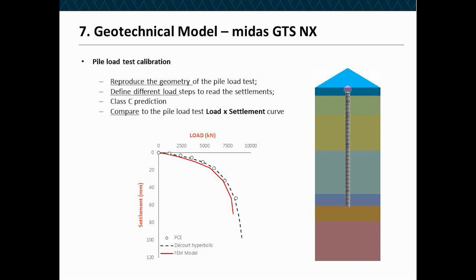The load settlement curve presented shows the pile load test results along with the finite element model created. The values obtained seem to fit well to what was measured. This kind of model might be tricky because it might need many attempts, but we really believe that this is the way to go. You have better information, a better model if you go this way.